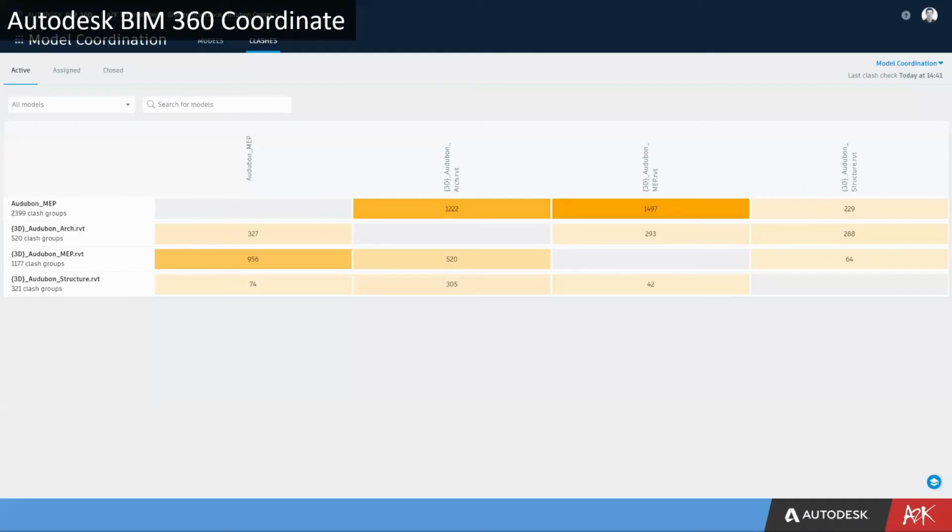Moving through the pre-construction stage, this is a space where you probably already appreciate how much the model coordination process plays into the design and pre-construction stages. But even that is evolving. The days of manual clash detection are fading in favor of more automated systems. Here we see a matrix of clashes within the project that has been generated without requiring any human input, other than making sure that the files are available to the system in the first place.